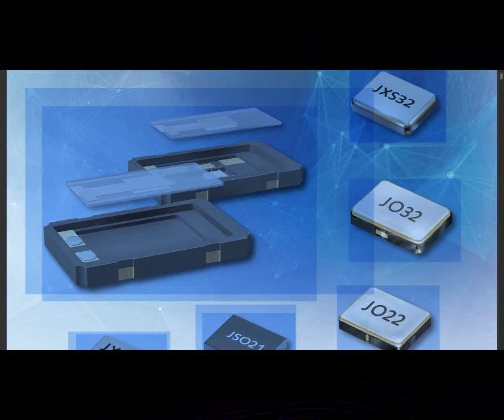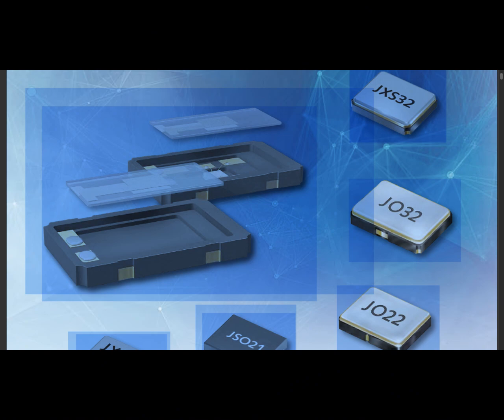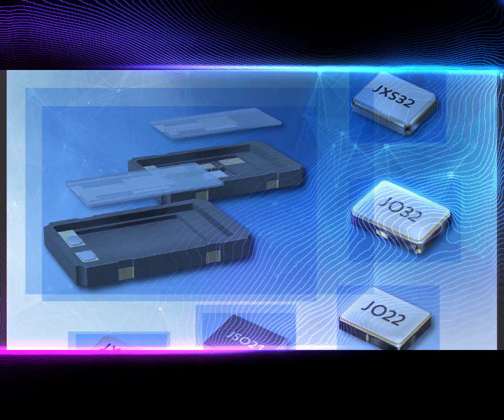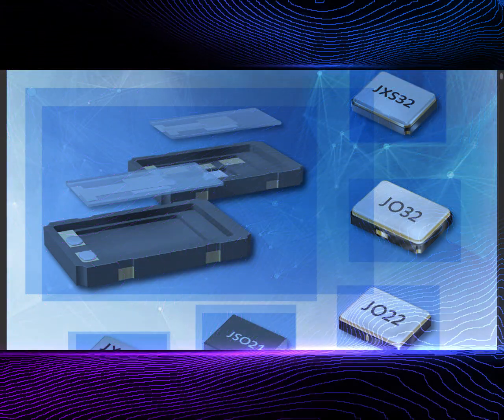In AT-cut crystals, the propagation velocity is about 3320 m per second. The required thickness d at a given frequency can be estimated as follows.